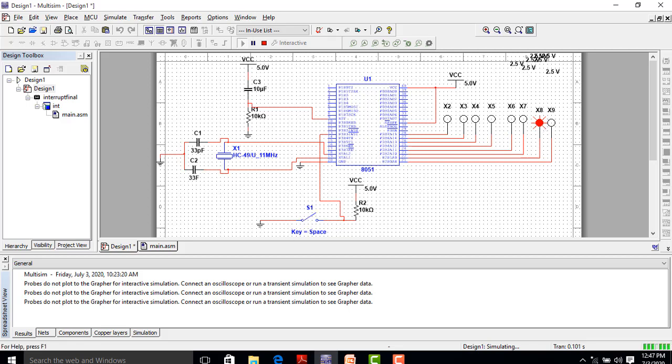Press it once again. These both should become 1 because it will become 3 in binary. Agree? Three interrupts have occurred. Now 4. What will happen? We'll move to this bit, right? So this should become 1 and this should become 0. So it will become 4. Let's do that. You can see that.